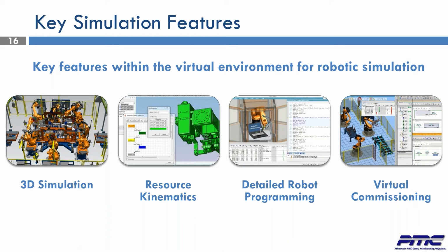So we can connect the virtual robot with a real robot controller, and we can parameterize its trajectory with real speeds, with real types of movements, with robot signals, with release signals, and some other parameters like gluing parameters or welding parameters. So this is the step of detailing the program before downloading and loading it to the real robot. We can also work with virtual commissioning. It means that we can validate the robot logic and the PLC logic within a control environment while still in the planning phase. In this case, we don't affect and we don't stop the real production environment.